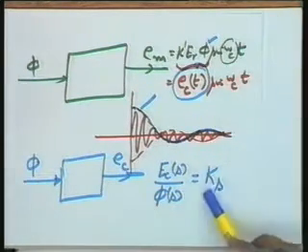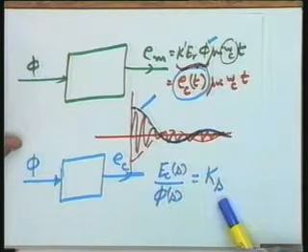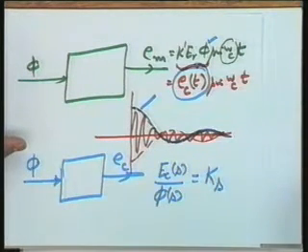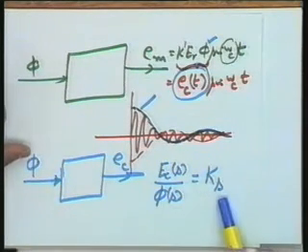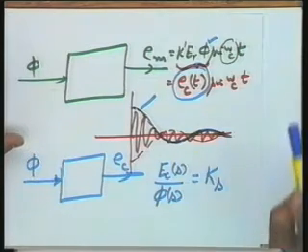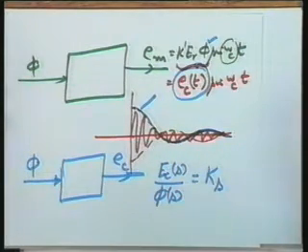So this constant Ks is important to me as far as the flow of information is concerned, and this constant Ks does not depend upon the carrier frequency. Okay? There was a little confusion last time as to why I am interested only in the envelope and not in the total information as far as mathematical modeling is concerned.